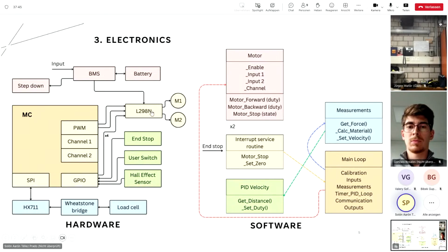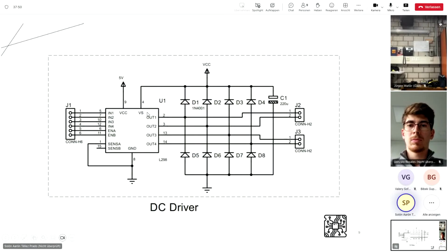The actuation block is made up of two motors, the linear advance motor and the drill motor. Both motors are connected to the controller using a driver. The power of both comes from the 7.6 volt BMS module, and the voltage of the drill motor is 7.6 volts, which is provided by the battery. It's not a problem. The linear advance motor works with 6 volts, and the control loop will calculate the appropriate PWM taking into account the upper limit of 80%.